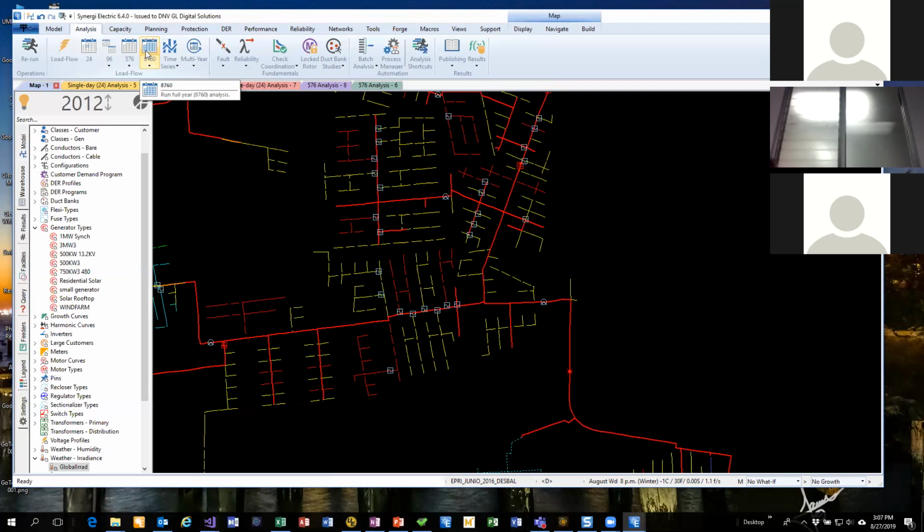I think that 576 is a much stronger approach because, no matter what we want to believe, there's engineering judgment behind all the data. All this data is collected, it's run through systems, it's got errors in it. And so just because we're running 9,000 load flows doesn't really mean the results are any better. So with the 576, I feel like the data is more compartmentalized. We know exactly what the data is, what it means, what the shortcomings are. And so engineering wise, I think 576 is better.